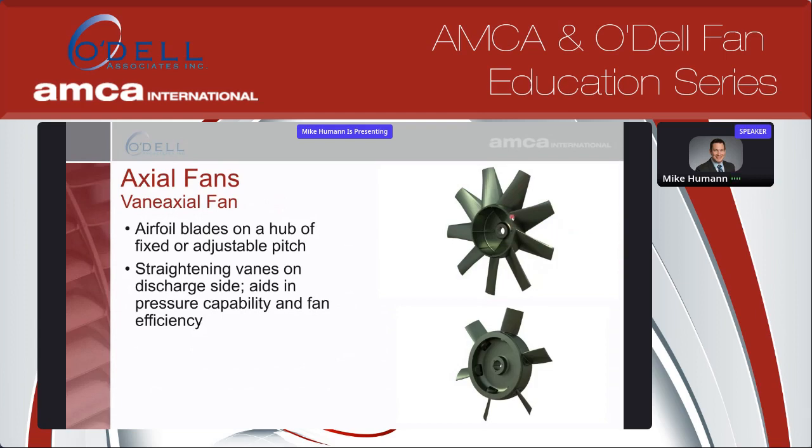The picture on the upper right here is actually a fixed pitch. So these are cast blades welded to a cast hub in a fixed orientation. And then down below, you actually have an adjustable pitch. These are cast blades again, but there's a pocket here, and these can actually be changed in the field at rest. So when the fan is stopped, if you need to tweak the performance because you may not be on a VFD, or it's a site that doesn't allow a VFD, there's certainly some flexibility here to change the performance of the fan as you change that blade angle.